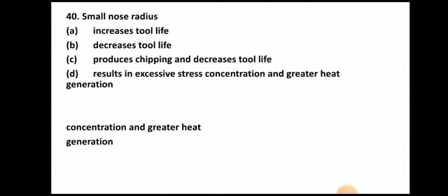Next question. Small nose radius. The answer is it results in excessive stress concentration and greater heat generation. So as you provide a small nose radius, there will be excessive stress as there is less material. So excessive stress will be concentrated there and greater heat generation will be there.